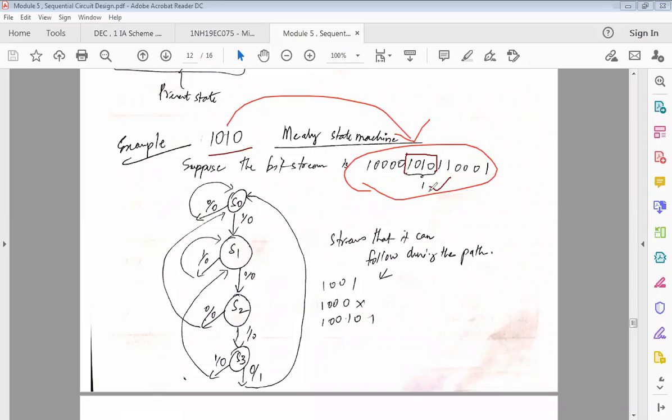It is just like this. All of you are standing in a line, and I am looking for one of your classmates. If I find one of the classmates, I will say, please step forward. So it's just like that. Here I have found this combination of sequence, which is 1010, and I would say that I have received one such pattern, so my output turns out to be 1.